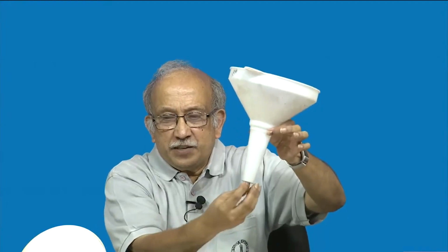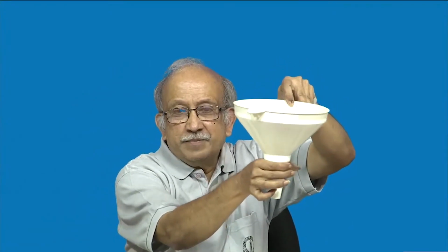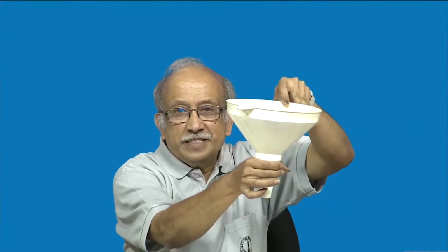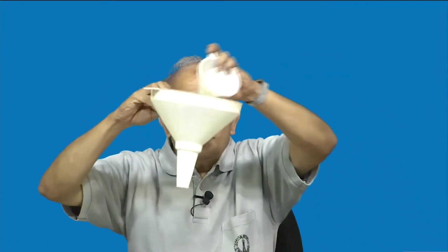So, there is a chance for the air to go inside and all that. Now, instead this has been made with small flutes all around here. There are small flutes here. So, when you put it in a jar or a measuring jar, air escapes out and we can easily pour the material inside. The magic is, all of the samples can be printed by rapid prototyping, and just by a simple scaling method you can even find out what the volume is.